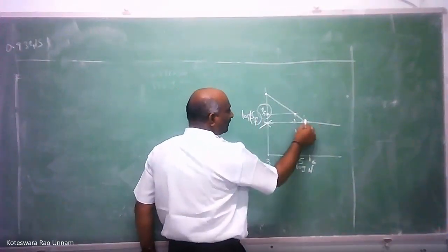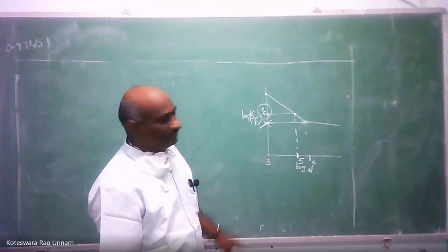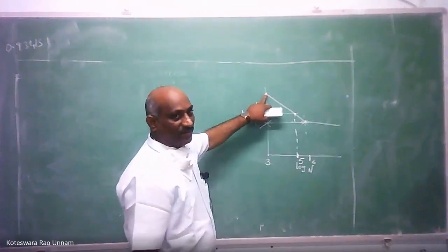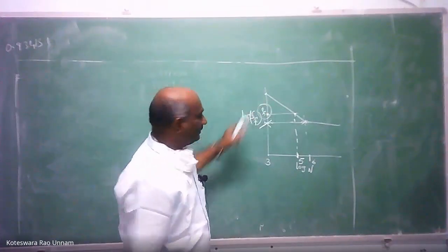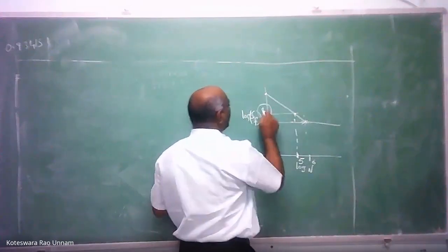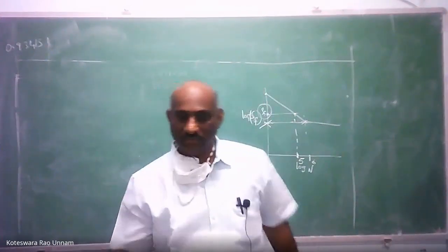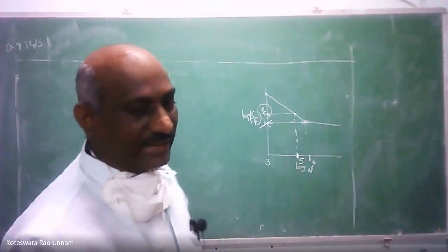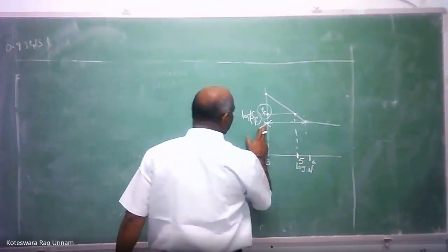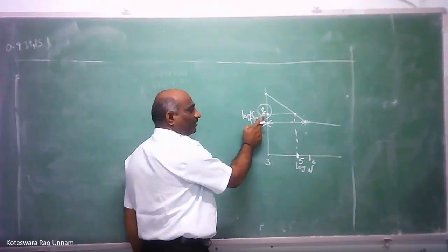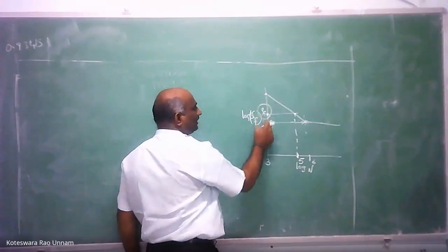That means you have to estimate the SE value, then identify this point. Then using this SN curve only you can find out the SF value. So even though your design criterion is not SE, to estimate this SF value you require SE and these points on this curve.